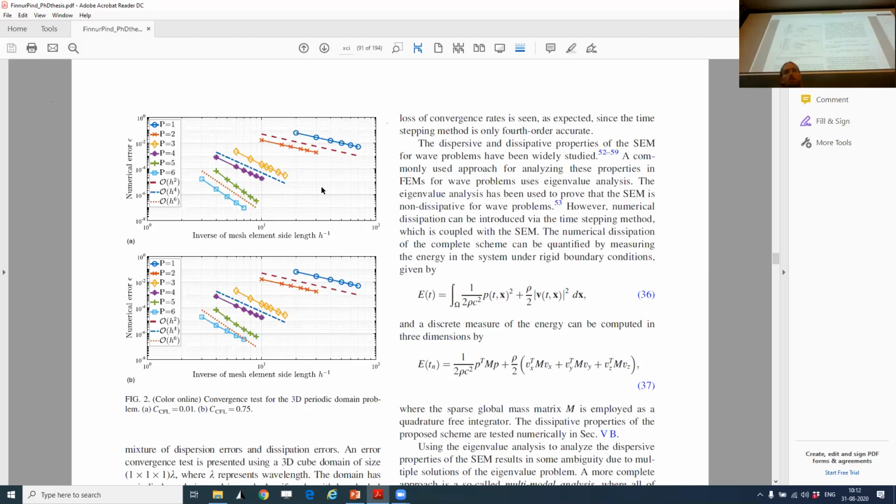I would say that DG-FEM is perhaps better suited here because what you can straightforwardly do with DG-FEM is that you can use different basis functions in different elements. So you can have, for example, fourth order discretization here near these details, and then up here you can have order 10 or 15 or whatever. Can you? Yeah, really so.